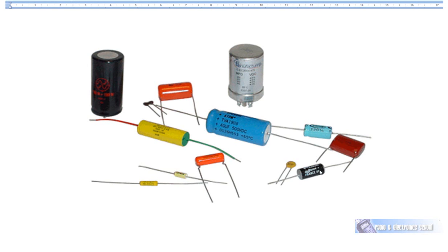This capacitor is polarized. It's an electrolytic capacitor. Likewise, this is a polarized capacitor. It must be connected with positive to positive, negative to negative, otherwise you will destroy the capacitance and probably do some damage to your radio.